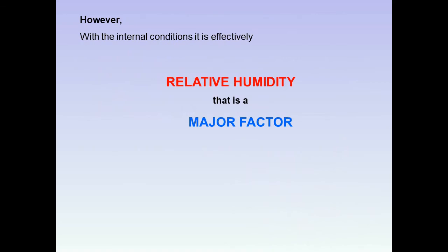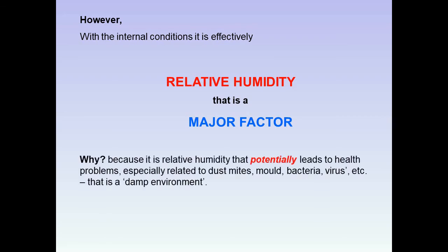However, with internal conditions, it's effectively relative humidity that is a major factor. Why? Because it's the relative humidity that potentially leads to health problems. That is what we would call a damp environment.